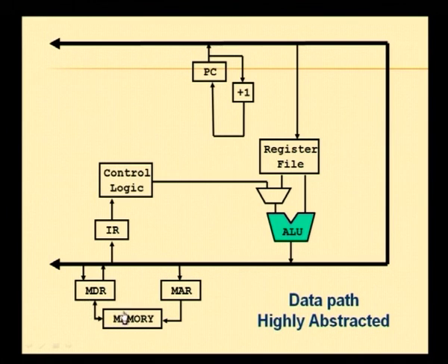That is, if it is a read operation, then on specifying the address, data from the memory will be stored in this data register, which can then be taken by the processor, either stored in a register or used for some other purpose. If it is a write operation, then along with specifying the address, you will also specify the data that is to be written into that memory location, and you give a signal called write to this memory, and the data will be written into this memory. Okay. If it was an input or an output device, it is not shown in this picture. Similarly, you will have some registers to which you will be doing a write or a read operation, depending on whether you want to input from the device or output to the device.